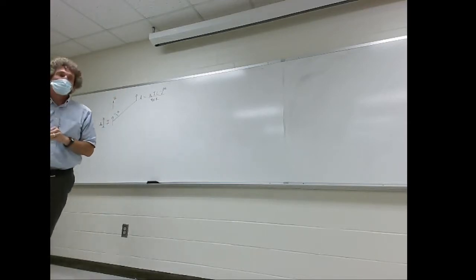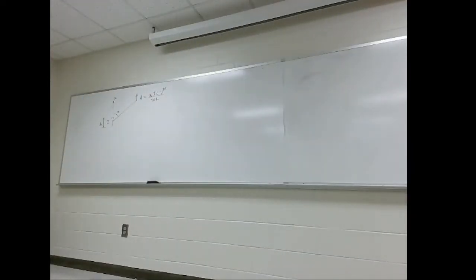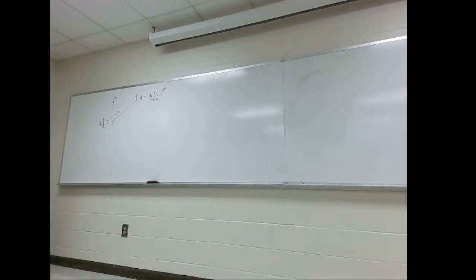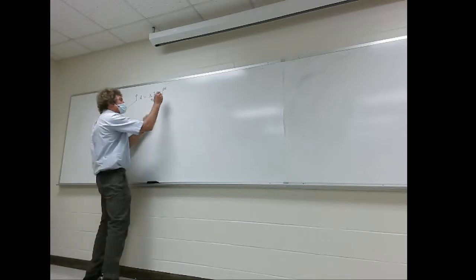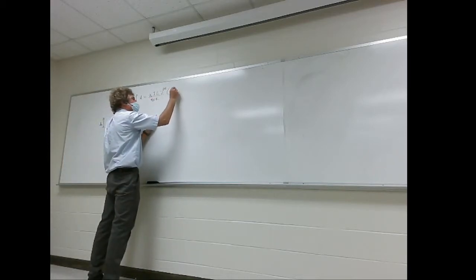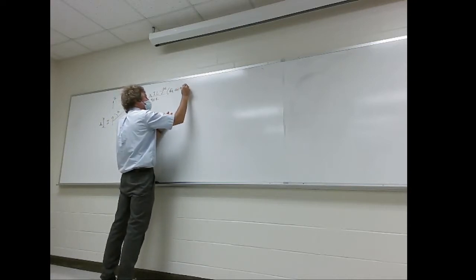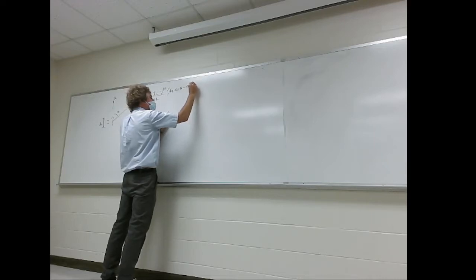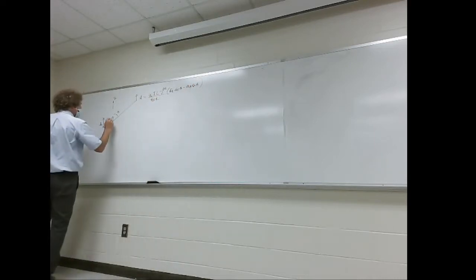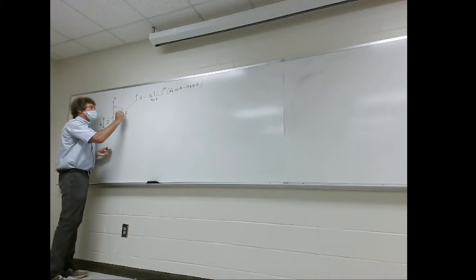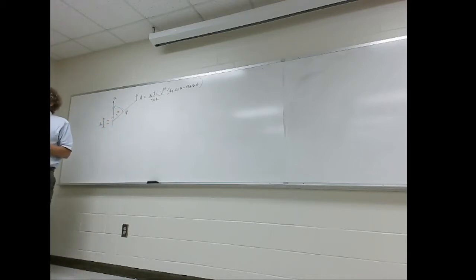What I'm going to do is put the spherical transform of AZ. For AZ, it becomes AR times cosine of theta, and then minus A theta times the sine of theta, where theta is the measurement of the angle to the radius vector R. I'm not trying to bore you with this stuff. I just want to make sure you understand how come there's going to be a couple other field components. Now this vector potential A, that's fictitious.